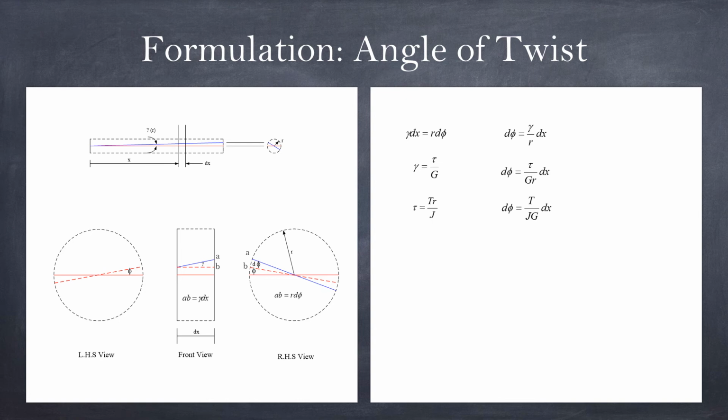Torsion will come from the free body diagram. Polar area moment of inertia will come from the cross-sectional area, which we already proved for the circular cross-sectional area. G is the material property, the shear modulus of elasticity, so we can have that before we need to know anything. It's going to be easier for us to do it this way rather than calculate the stress first. So in a way, there we are.